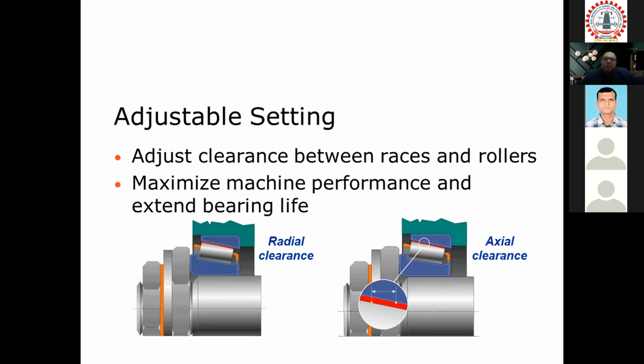Okay, I'll go one by one. I think your first question is about the lubrication. Does it require lubrication? The answer is yes, because if we run without lubrication, it will immediately be a catastrophe. It will fail almost in no time, maybe in a few minutes itself. There will be metal to metal friction and a very high amount of heating and burning over there. So there will be a seizure.